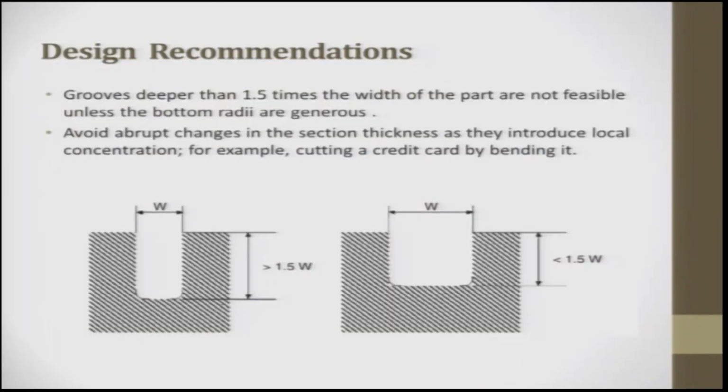Again getting back into design recommendations. Grooves deeper than 1.5 times the width of the part are not feasible. Many a time, what happens is you want to have a blind groove. What people generally do is make a through hole and then put a closure and close it, one way of doing it.